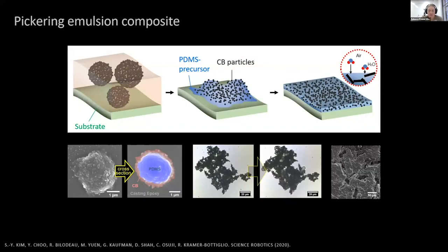These are kind of unique sensors due to their non-toxic fabrication process. So typically conductive composites need to be thinned with a compatible solvent, such as cyclohexane, which is what we use to manufacture the exfoliated graphite-based sensors that I talked about earlier. Here we use ethanol as the carrier solvent, which only suspends the Pickering emulsion particles. And upon deposition, the ethanol evaporates away and precure polymer particles spread out into a conductive film.